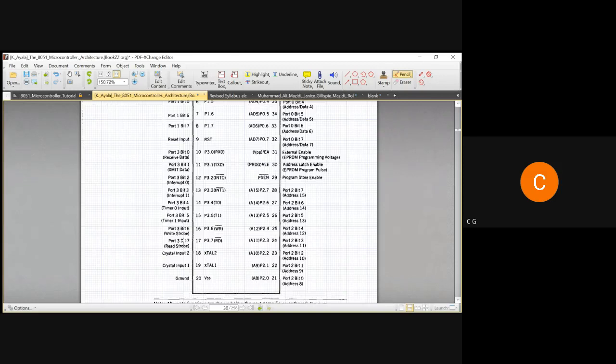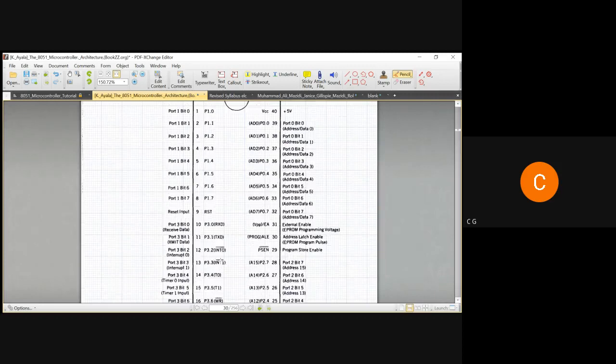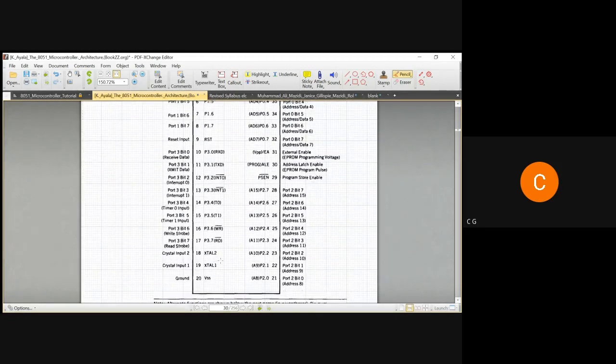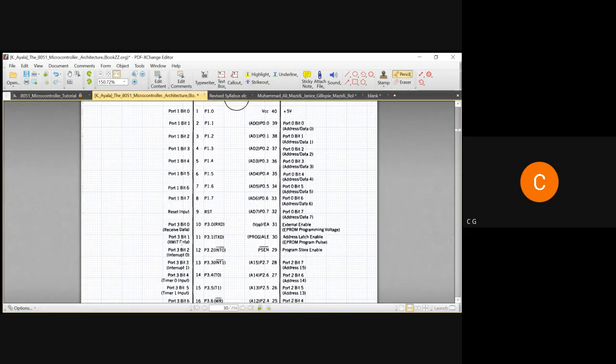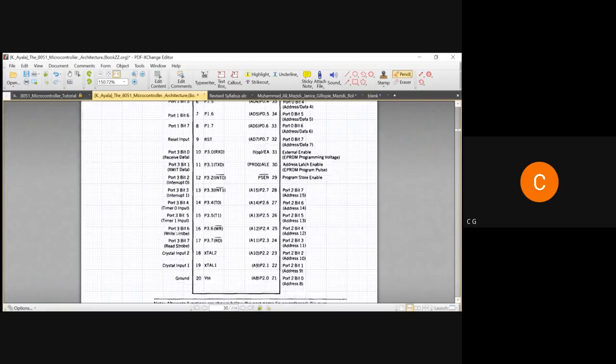We look at a port as an input or output, but it is also associated with things like INT0, INT1, write protect, read pin, write pin. Certain pins of the port are associated with interrupts, but we study interrupts as a separate entity and ports as a separate entity. So first we have to understand the role of the port, and then how the pins are assigned to that particular port.